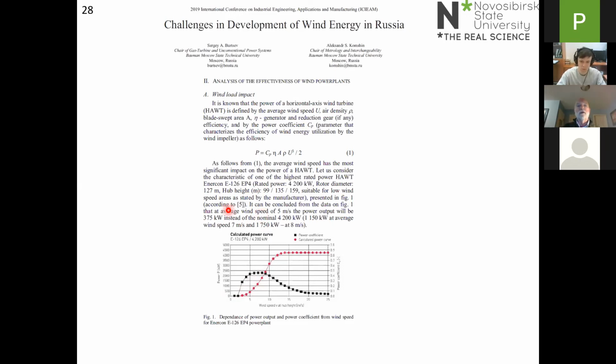So what these authors have done is to use a long-term average wind speed with effectively a short-term average power curve. And that mismatch in the time period of the averaging makes the mistake that they've got there.